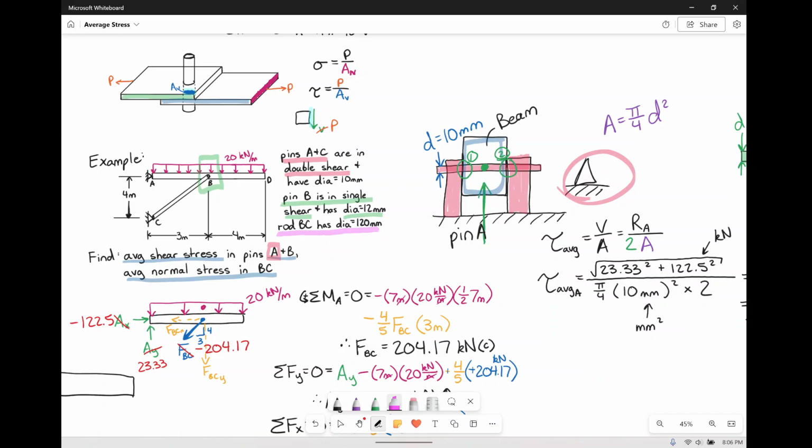The thing that was in shear stress were the pins holding it together. So usually when we're talking shear, we're really not talking along the face of the object. Usually, sometimes we are. But in the case that we have connections, shear in the pins is talking about the connecting pieces themselves. So just pay attention to that.